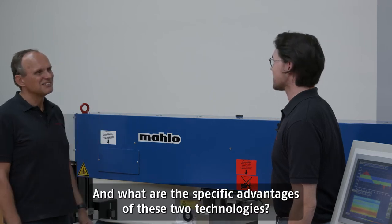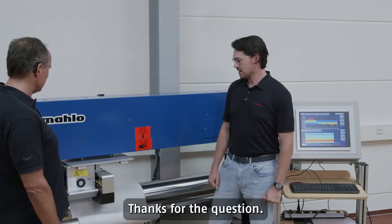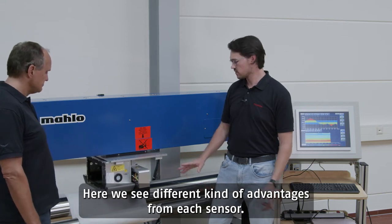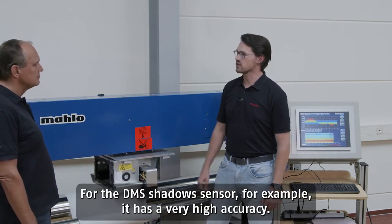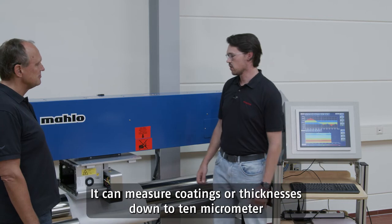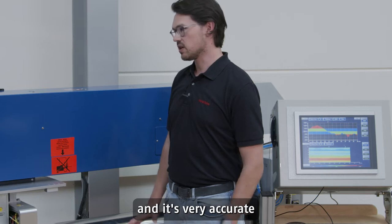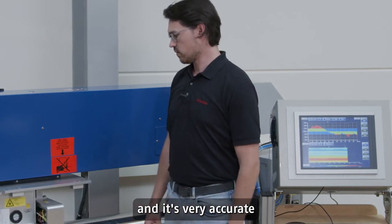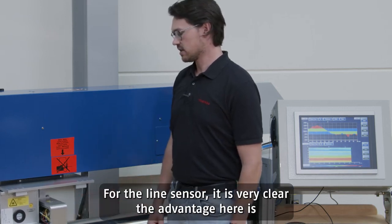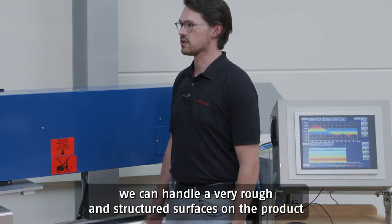And what are the specific advantages of these two technologies? Thanks for the question. Here we see different kinds of advantages from each sensor. The DMS shadow sensor, for example, has a very high accuracy. It can measure coatings or thicknesses down to 10 micrometer and is very accurate depending on the product. For the line sensor, the advantage is very clear: we can handle very rough and structured surfaces on a product.